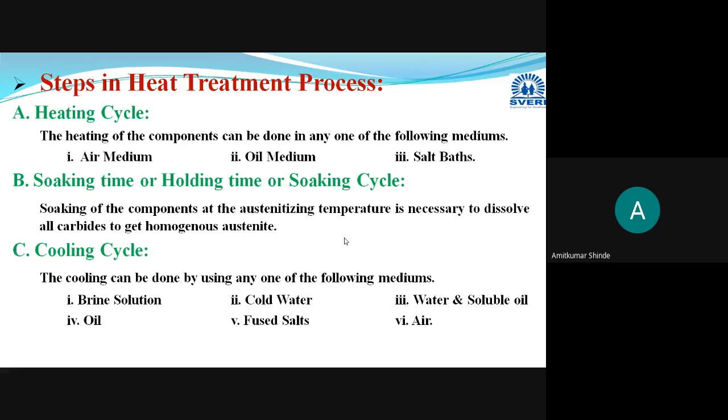And which care do you have to take here? You have to use a controlled atmosphere to perform the heating process, like an inert atmosphere, using some inert gases.